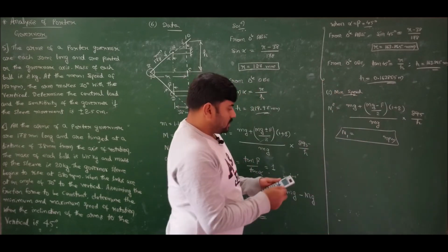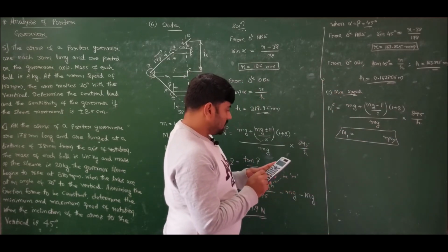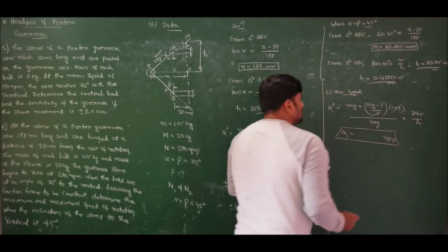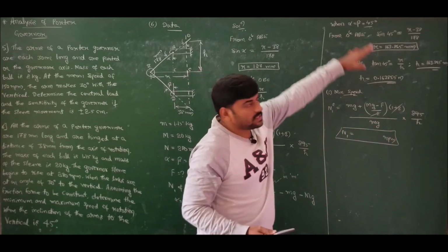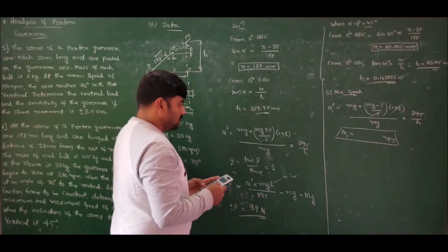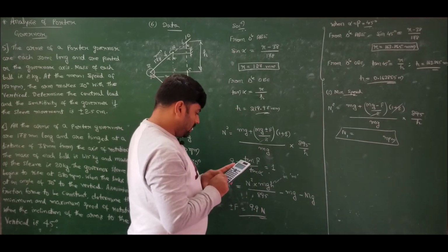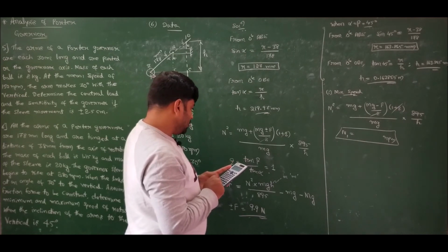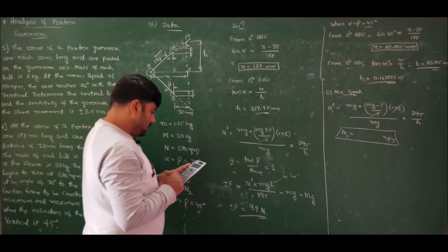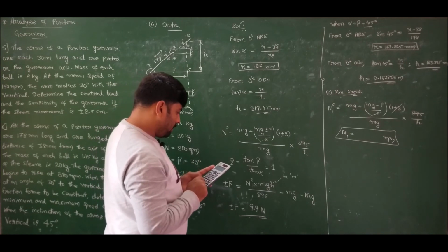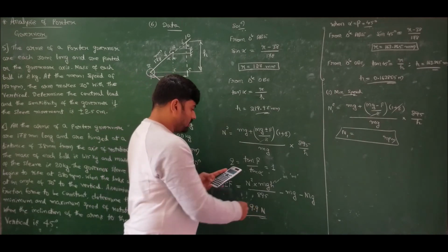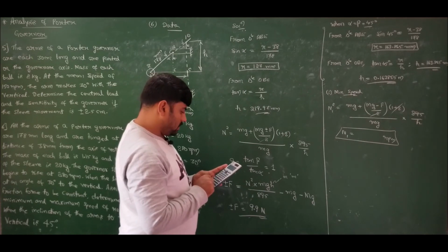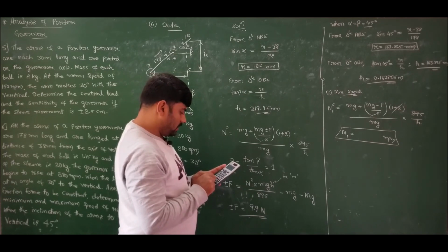So therefore how much is N1? We know all the values. These two and this will get cancelled because Q is equal to 1 because alpha is equal to beta. Now mg is 1.15 into 9.81 plus capital MG, 20 into 9.81, minus 9.9 which is the friction force, divided by mg, 1.15 into 9.81.